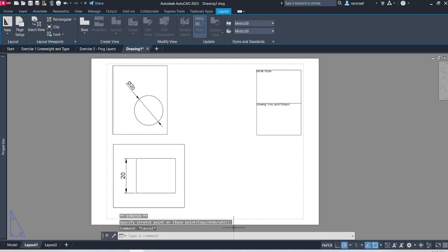So this is useful if we have a very large drawing with many details and I want to zoom in on different portions of it. Maybe have many pages, one with the whole thing and then another page with just some details. I can have multiple viewports looking at different parts of those drawings. And on all of them, I can put in a title block quickly and easily without having repeated title blocks on my drawing.